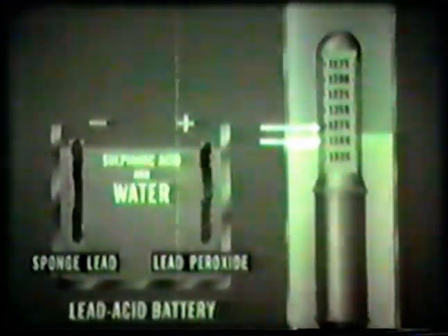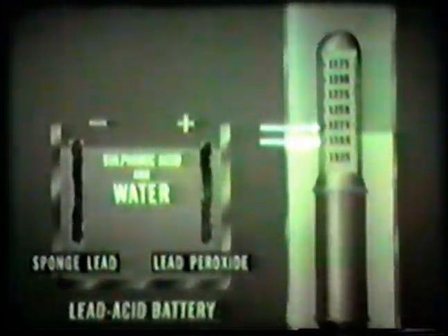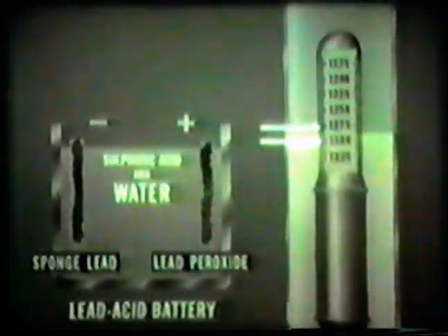As the battery is discharged, the acid in the electrolyte is depleted. When the battery is in a medium state of charge, the float will sink deeper into the electrolyte so that the reading will be between 1240 and 1275. Any battery showing a reading of 1240 or lower should be recharged or replaced with a fully charged battery.